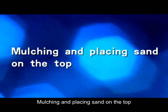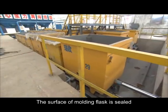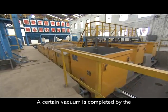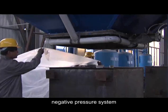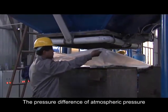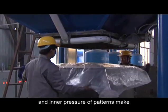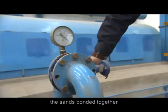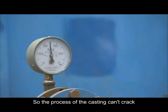Mounting and placing sand on the top. The surface of the molding flask is sealed with plastic film. A certain vacuum is completed by the negative pressure system. The pressure difference of atmospheric pressure and inner pressure of patterns makes the sands bonded together, so the casting can't crack in the process.